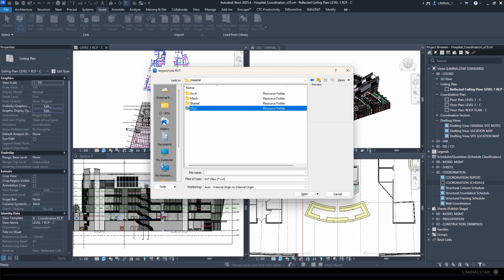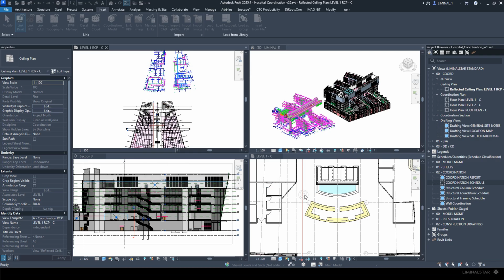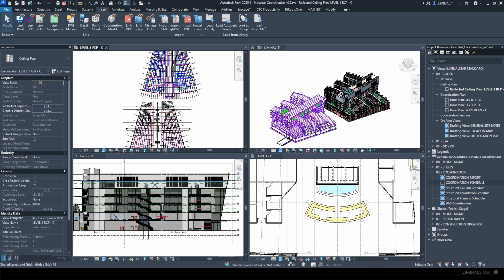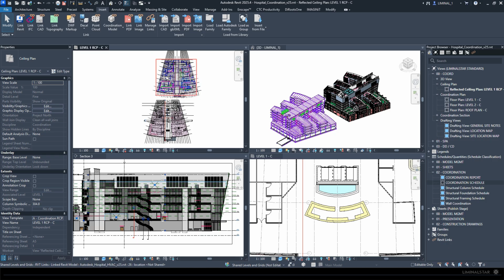Now, if you're a Revit purist, you're probably saying to yourself, why didn't he coordinate the project base points and the survey points? And that's an awesome, really astute question, and I probably should have. If this was a real project, I would be trying to get that done. But the project base point isn't as important if you're not using certain tools like spot elevations or spot coordinates. If you are using those, then it is important, and you're going to want to make note of that.